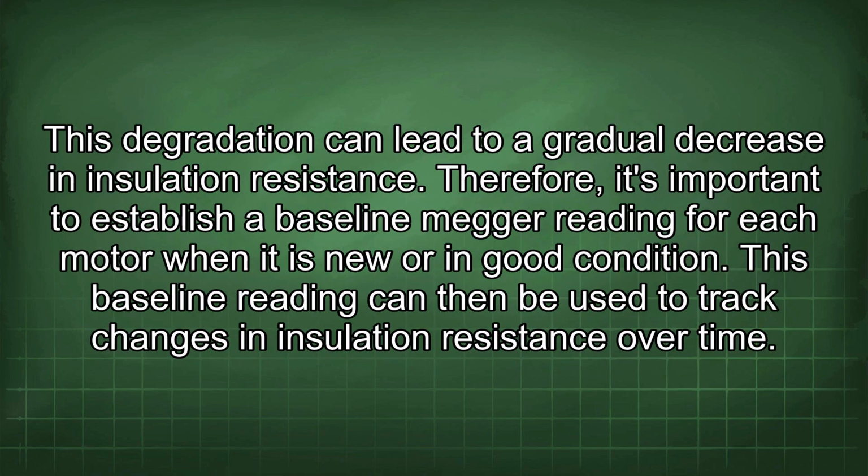This degradation can lead to a gradual decrease in insulation resistance. Therefore, it's important to establish a baseline Megger reading for each motor when it is new or in good condition. This baseline reading can then be used to track changes in insulation resistance over time.